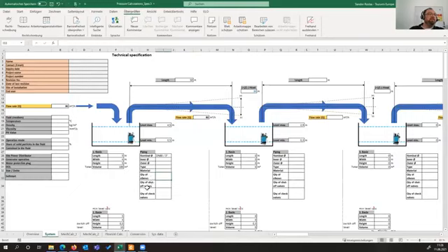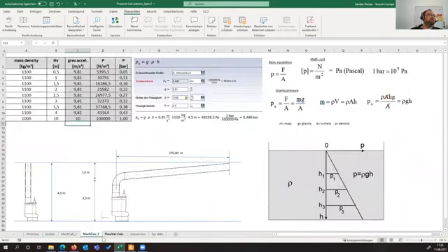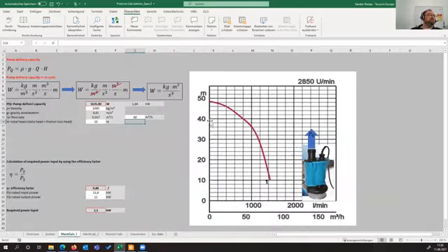Do we have to consider any shut-off valves or check valves in that system? All this info and equipment will finally have an impact on the friction loss calculation and what we have seen here on the total delivery head of the pump.